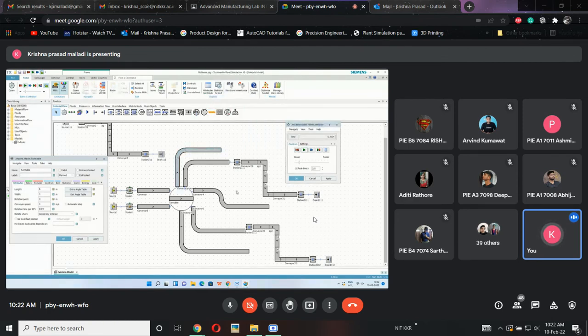So once I have defined the angle, I can check. See here, once the part entered. See, now this is the angle. So based upon that, I can modify my bridge like this. It was done. Now both are connected. Now I will be checking the third one, collecting the part. Yes, it was perfect. If you want to move the conveyors, you can also use the arrow buttons on your keyboard. You can use upward, downward, forward and backward, so that it will be moved.